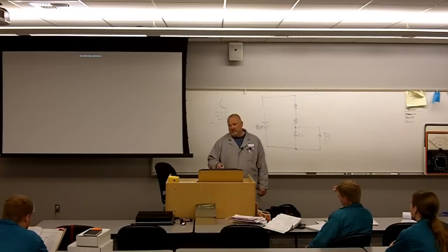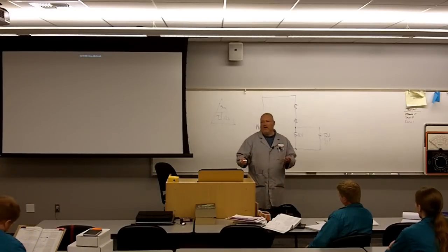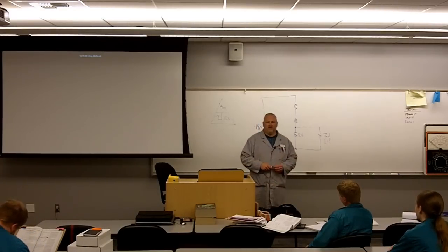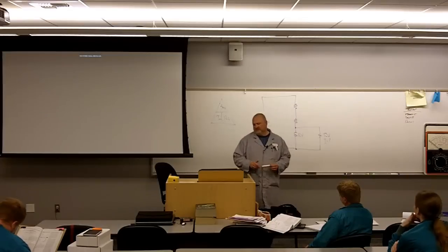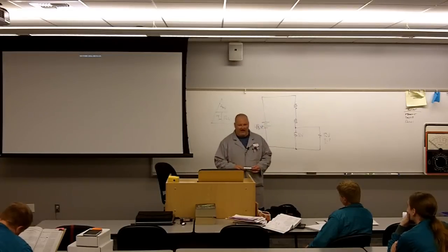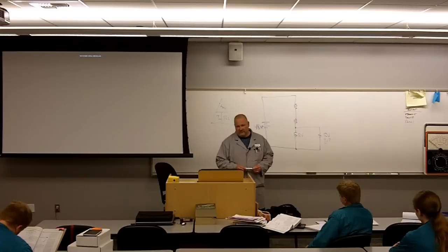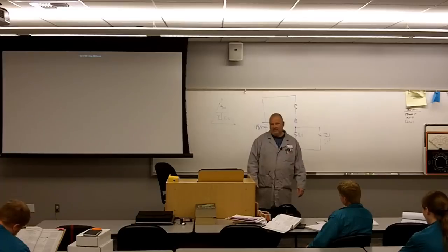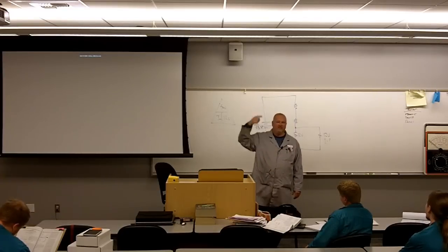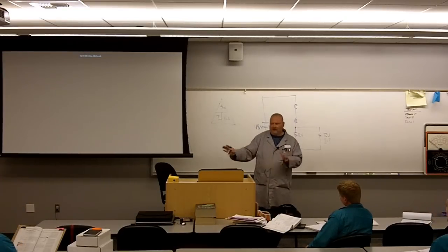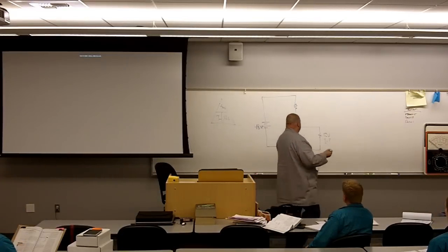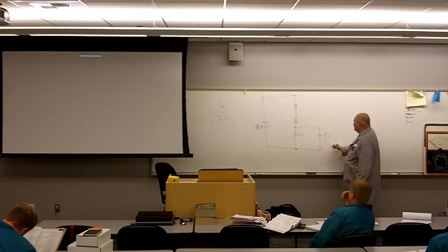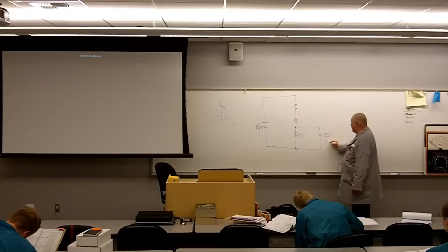So what I'm going to do with this, just for the case of example, is I'm going to round this. Generally speaking, a CB radio is going to take a minimum of half an amp at 12 volts. A minimum half an amp, and probably even more than that. But in order for it to transmit out 5 watts, you see the math. Does everybody see the math? Okay. So I am going to assume that this here is 0.5 amps.